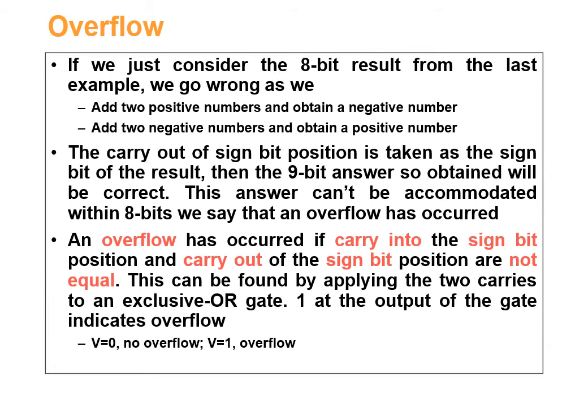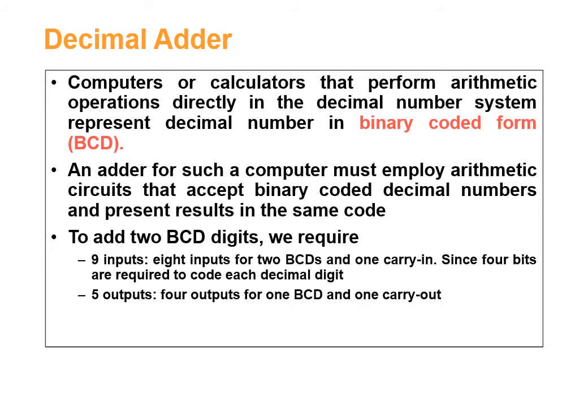The binary adder-subtractor circuit with outputs C and V. If the two binary numbers are considered to be unsigned, then the C bit detects a carry after addition or a borrow after subtraction. If the numbers are considered to be signed, then the V bit detects an overflow.